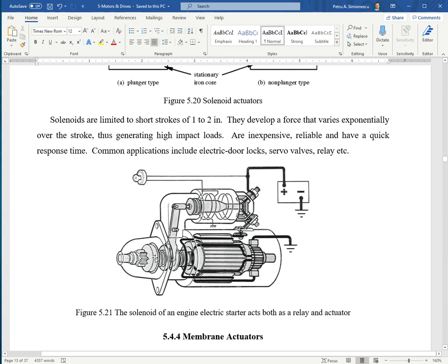It has a one-way clutch, and moves its pinion into contact with the ring gear on the flywheel. By doing so, you run very low current through the ignition switch, and you have a short, thick wire connection going from the battery to the starter. The circuit closes through the chassis. The minus is the ground, the chassis of the vehicle. Okay.